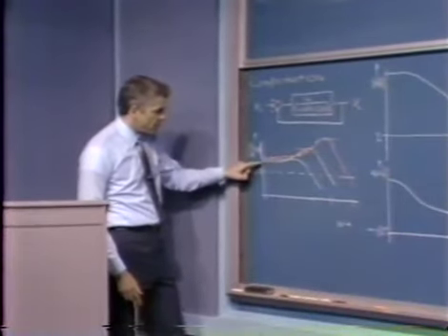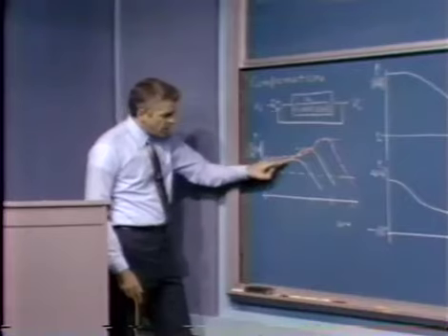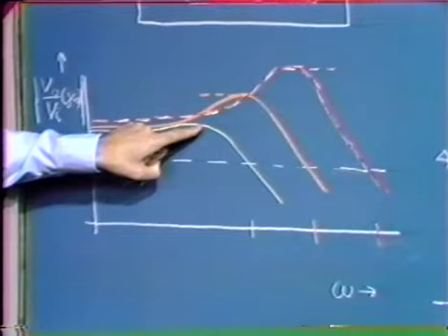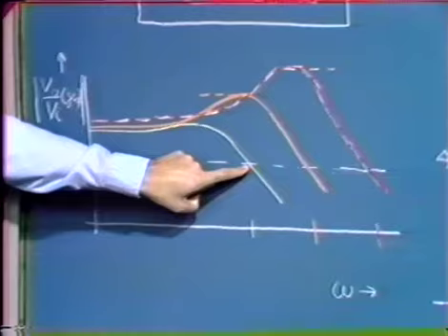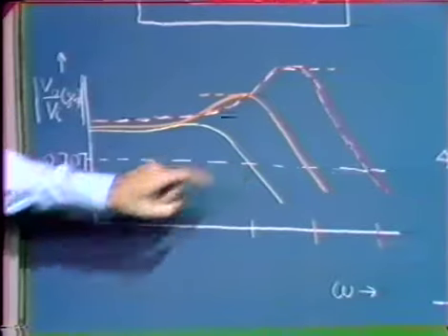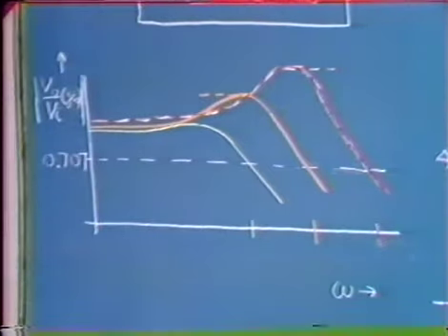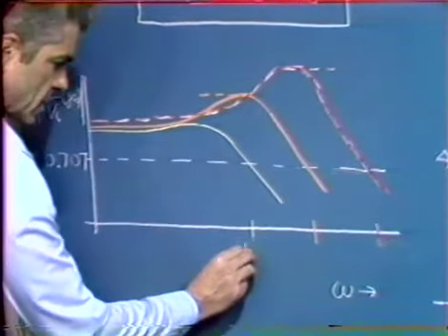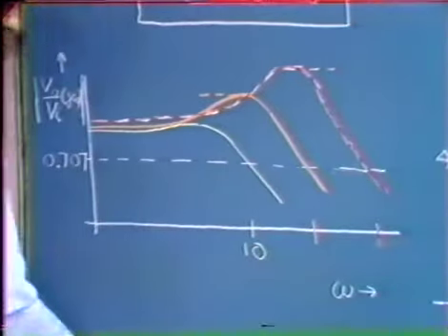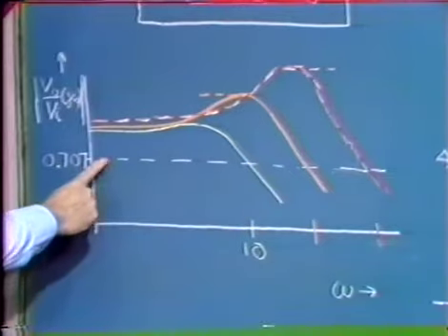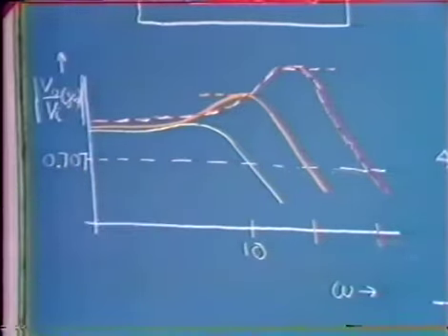We start out at about 0.9. The magnitude peaks up just a little bit, reaches a magnitude of about 1, as we saw from the Nichols construction, then drops off to 0.707, or 0.7, and we said that occurs at a frequency of about 10. So on our omega axis, for this particular system, we have a magnitude of 0.7 at a frequency of 10. We're able to determine a good bit from this kind of construction.